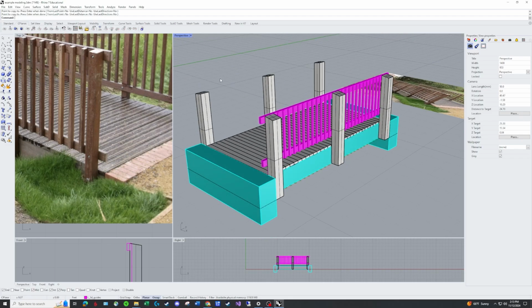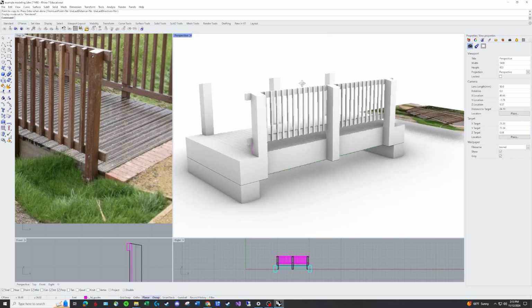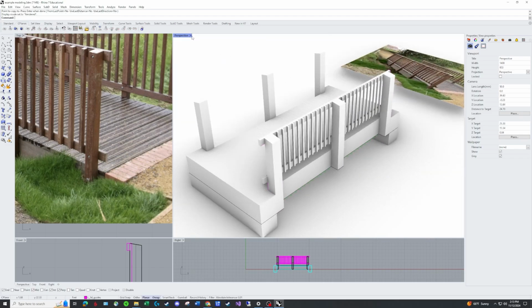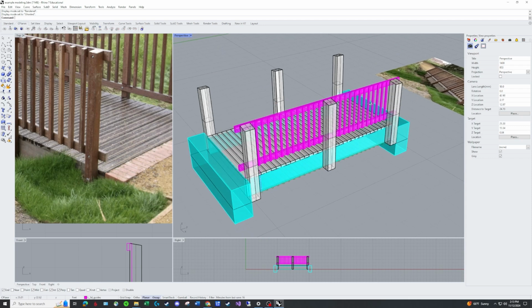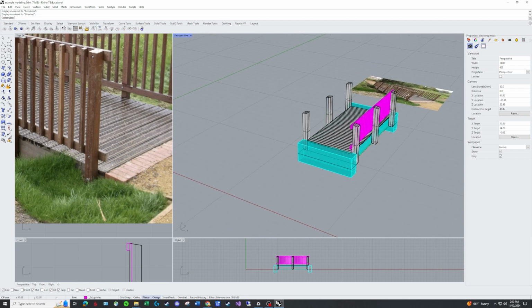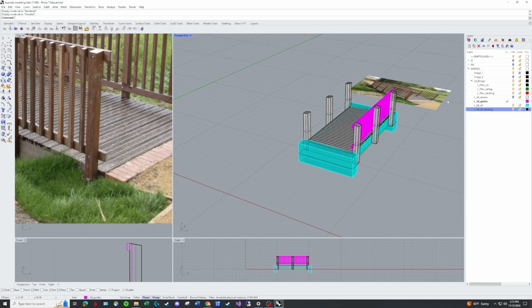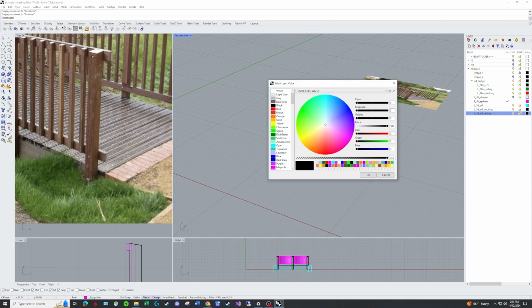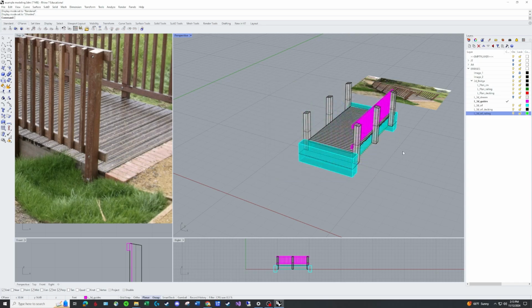And there's your railings. And I always like to do a little render. Doesn't that look lovely? And now we can go back to I have got to mirror this. Now there's a lot of stuff to select, so my strategy is, I know this is on guides, there's probably some issues with some 2D or some 3D line work on that layer, so let me do railing, and then I make this a color where I know what it is I'm dealing with, so I'll make that green.